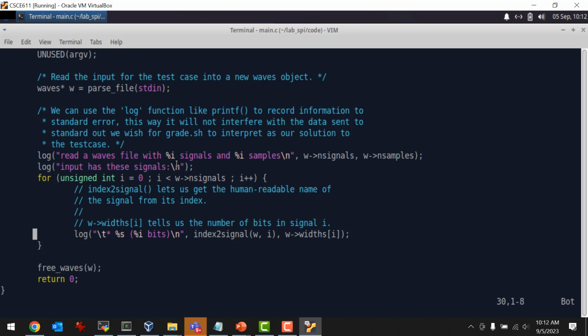And by scanning time, I mean you'll have a time variable, and then you can initialize it to 0. And then, as I mentioned last week, there's two functions you can call. There's find next edge, where it'll find the time index of the edge of a signal, rising or falling, or both, or I should say either one. And then there's a signal at function, which will tell you the state of the signal at that time. So those are the only two functions you have to use for reading the file, and then you'll have to put loops in there to basically go through the files and interpret the values.